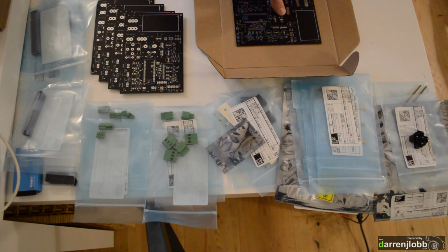So we've got the PCBs here. The heart of it is obviously your Arduino, which is a Nano. That's the piece on the top there. I've actually got it connected to an Ethernet shield there. It depends on how you want to connect, if you need an Ethernet shield. If you're doing it over serial or USB, obviously you don't, which is how the majority of people are doing it. I'm actually hoping to connect this over UDP, so over an Ethernet cable, which is what the shield's for. So you've got the Arduino Nano, that's going to go in the middle.